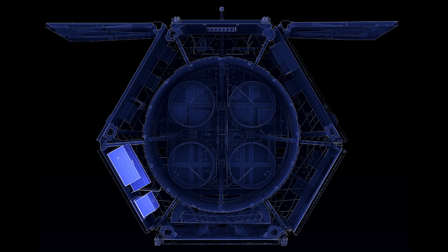Solar cells on the solar array panels will convert sunlight into power to provide approximately 4100 watts to the observatory's electronics while shading the spacecraft under it. The system includes a battery to regulate the voltage to all electrical components and provide backup power when there is no sun available to the solar array. This will not be used often because the observatory's orbit at L2 will keep it in full view of the sun at all times.